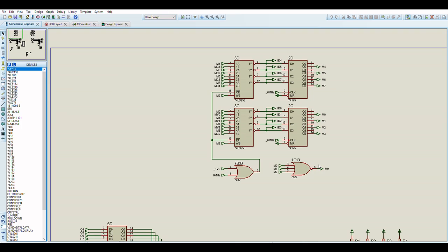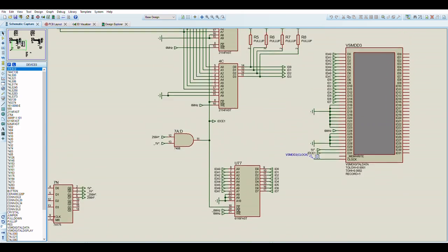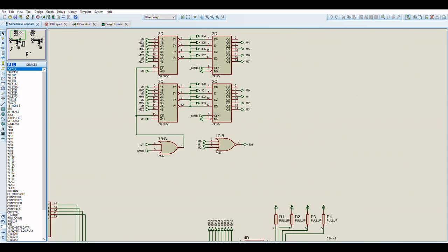If it's not transparent, if the current data in the scanline RAM is not transparent, this means a previously calculated opaque sprite pixel exists at that particular coordinate.